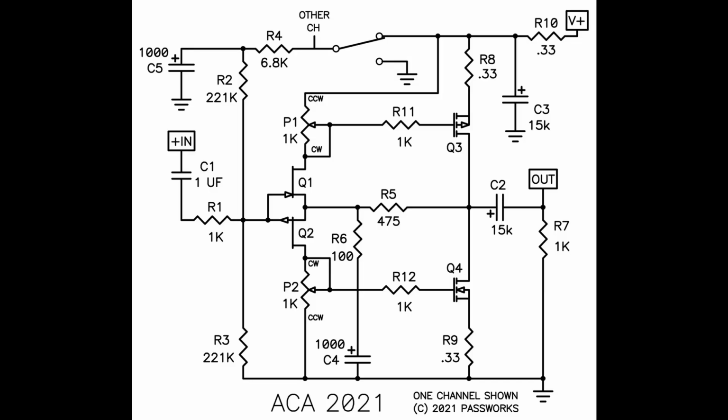Lastly, we add the details that show the final circuit design. R1, R11, and R12, all 1 k-ohm resistors, are there to prevent parasitic oscillations in the transistors. These transistors are very fast, and if you don't slow them down a bit with these resistors, there tends to be trouble at very high frequencies.